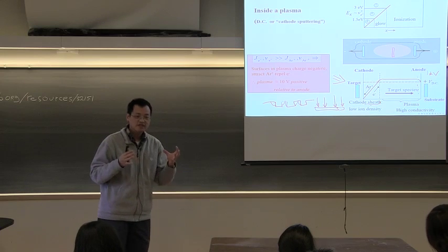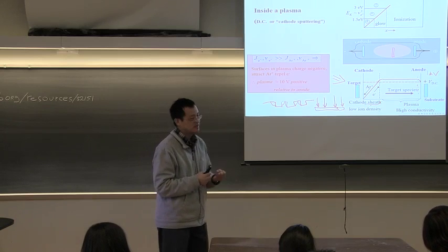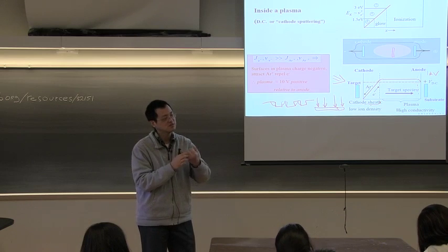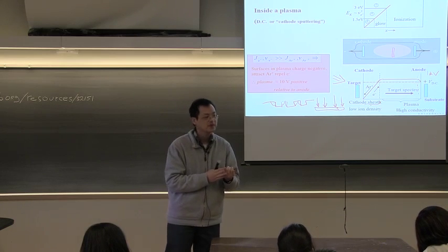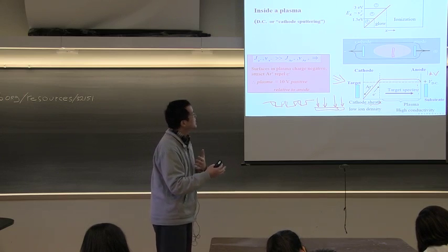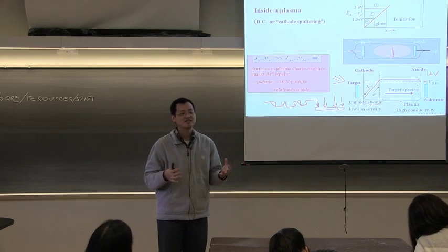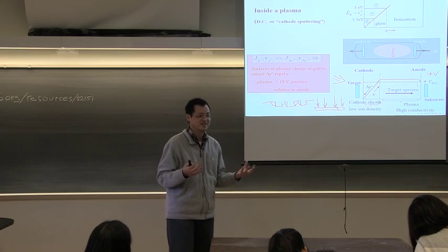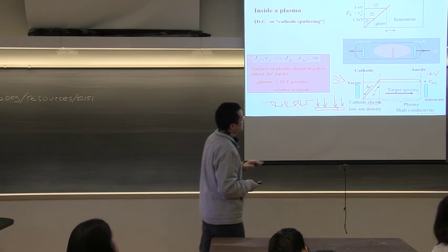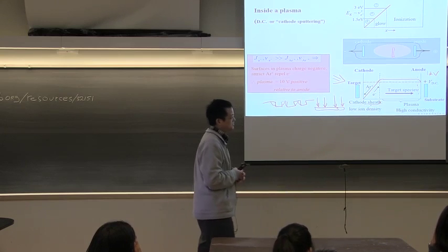So now we have a little bit better understanding of what's happening inside of the plasma. Basically, we know that the plasma can only be sustained in a certain pressure range, 10 millitorr to 100 millitorr. And then it's also conductive. But that doesn't really answer why we like it, right? Why does the semiconductor industry love the plasma? What does it do? What I want to show you is this important part, look at this, the potential of the plasma.